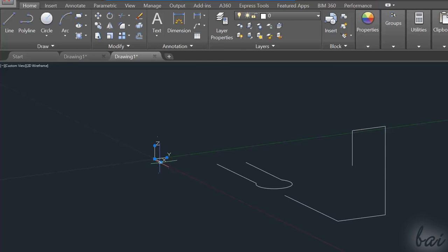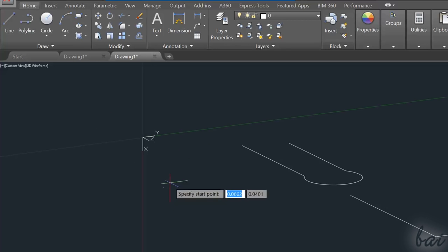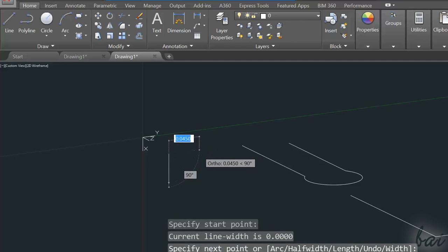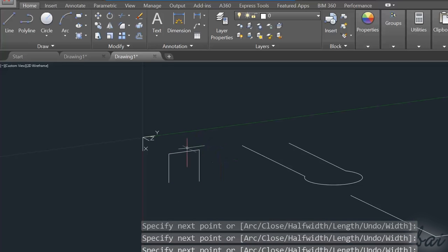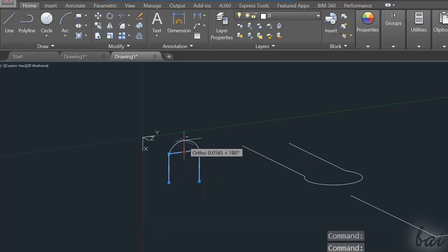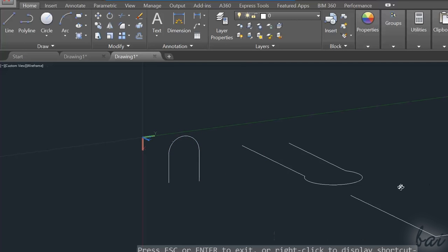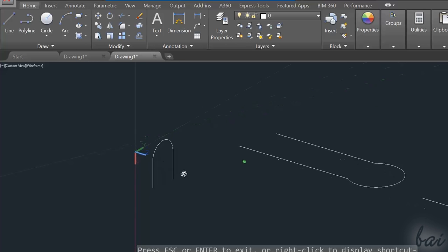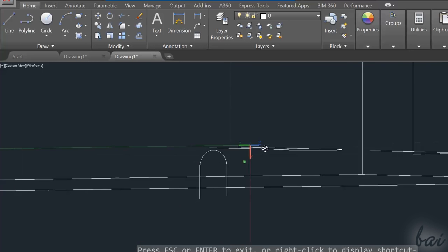The only way to draw all 2D objects through the z-axis is to rotate the main gizmo system. In fact, if you rotate it, you will also change the orientation for the x, the y, and also the z-axis. This allows you to draw 2D objects following this new orientation, so along the old z-axis orientation.